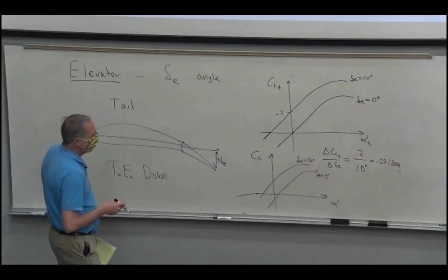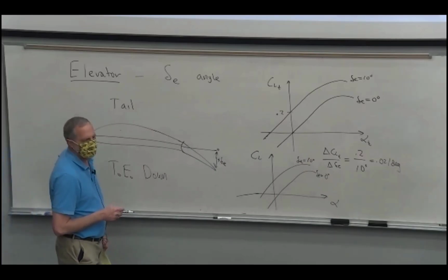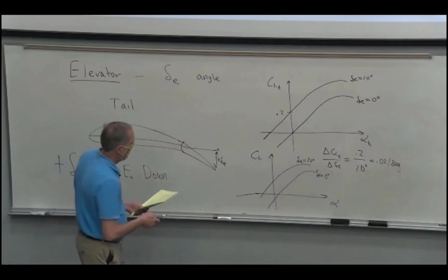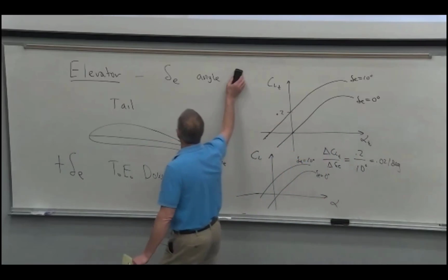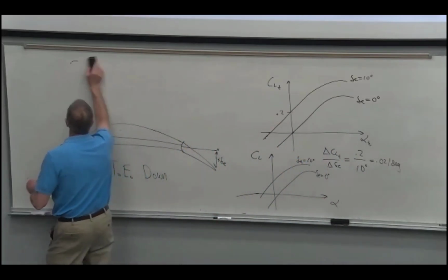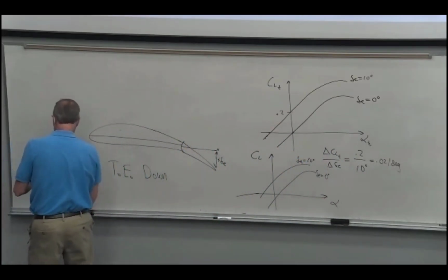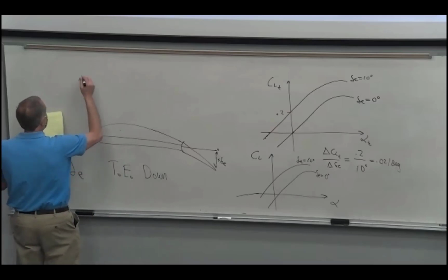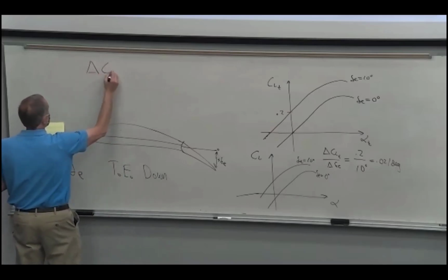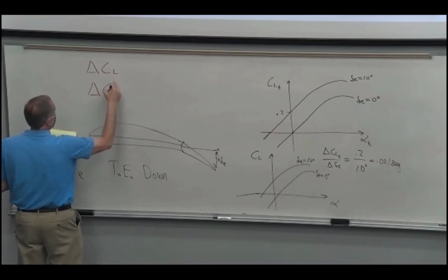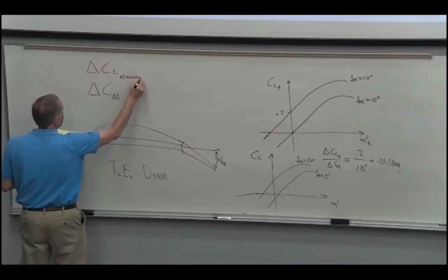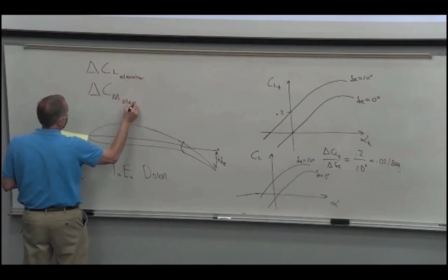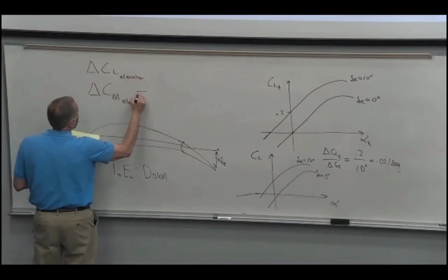And we could also measure the total pitching moment of the airplane for different elevator deflections. And what we would get is information on how the elevator affects the lift and the pitching moment. And so we'll say, well, we're just going to add on the extra lift of the elevator and the extra pitching moment of the elevator.